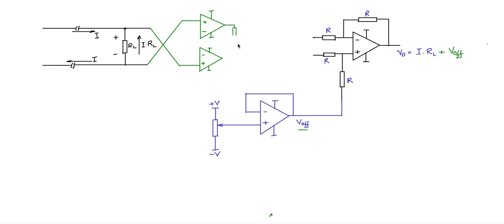and I will have 3 resistances connected in this fashion, and the negative or the minus terminals I will connect to this point, and this minus terminal I will connect to this point as indicated by the arrow cursor. So this is the connection that I would make. So this is a high input impedance instrumentation amplifier topology, which will give you a difference of this across this with a gain. So let me illustrate.